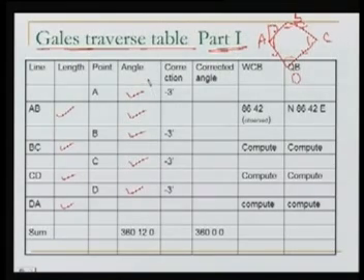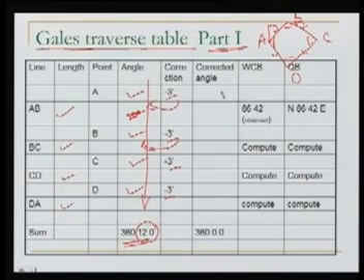Now what we do, we apply the correction for sum of these angles. Let us say I sum up these angles and the sum comes out to be this value. This is wrong because there is an error here. So what we need to do, we need to divide or distribute this error in all the angles. So the distribution in this case will be -3. So this is the correction value. We apply this correction to these individual angles and we will have the corrected angles. So we know now the corrected angles. So if we sum up these corrected angles, the sum will be 360.